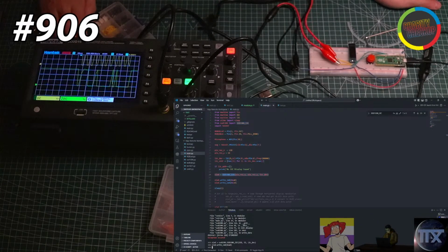So many times when you're working on something, we would be able to find what was broken, or if you had a bad solder joint. This is a good I2C signal, not too much noise. Anything more than this, it's probably going to have errors, and then it's your solder, not the software. So far, the multiple points of failure.